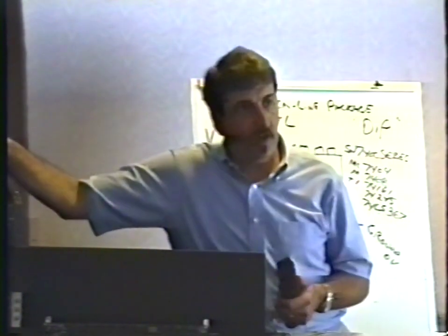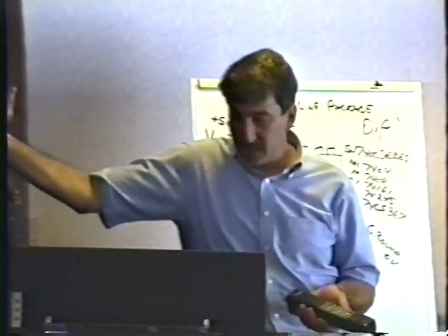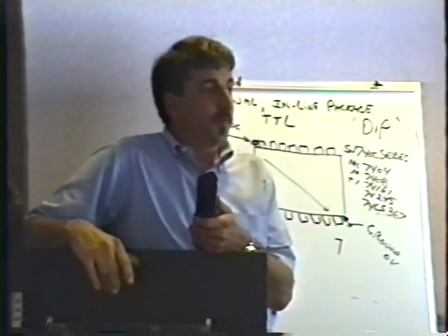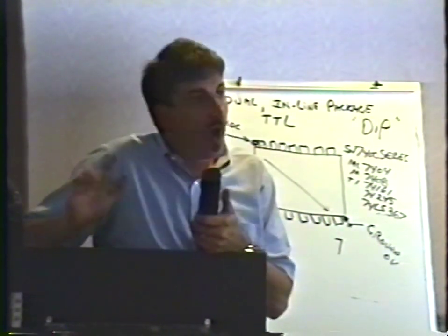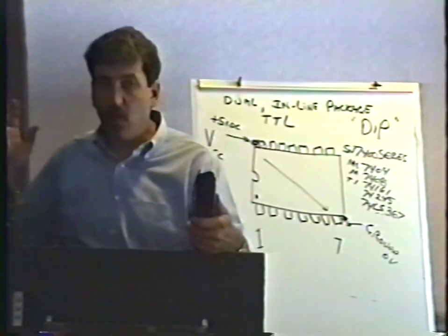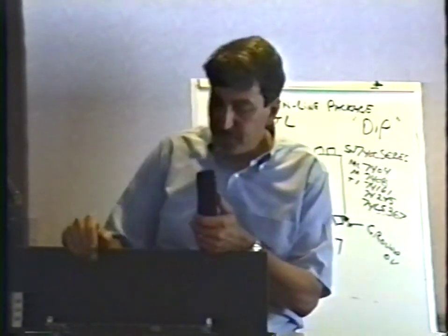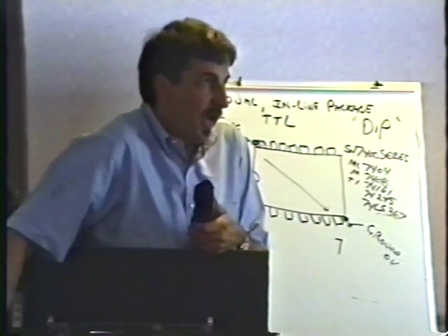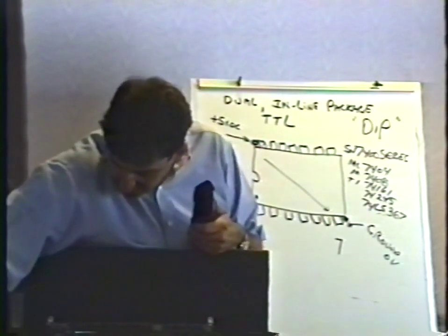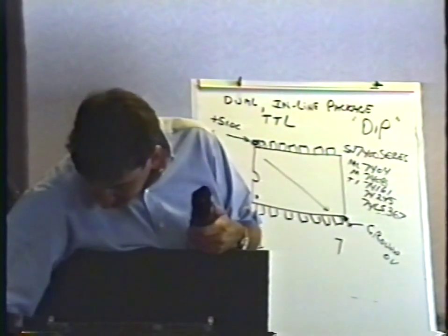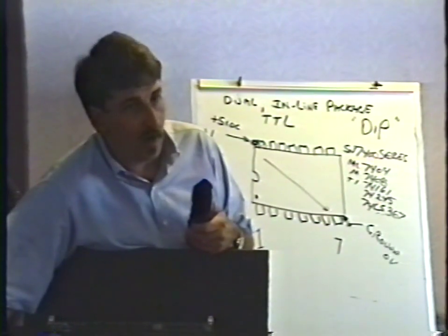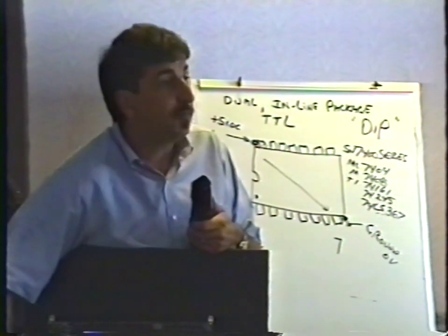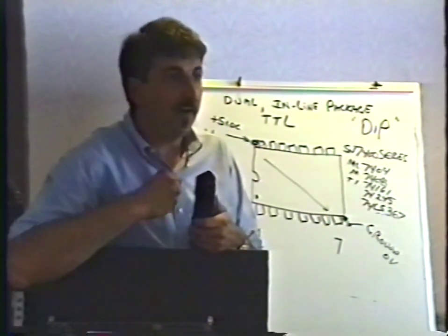Okay. Then when you... This was really cool. This is a typical kind of thing that comes into the shop. First of all, the power cord was bad, so I put a little temporary power cord on there, and it's working. So then we got the marquee up. No coin, the screen was blank. I coined it up, no game sounds whatsoever. We go over here to the connector, 3.7 volts. Not enough, obviously. With the meter connected here on the connector, I adjusted up the power supply. I don't know whether someone was messing with it or what, but it was way too low. Cranked it up to 5.1 volts. Fired right up.